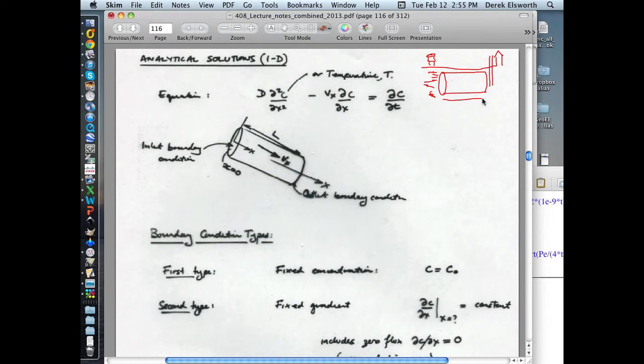then this happens to be the length from the source region to the compliance point, which is the length of this core. There's a velocity, which is an advective velocity along the length of it. And we'll take an x-coordinate that goes through it from upstream to downstream. This point here is x equals 0. This point here is x equals L, uppercase L. And we can try and solve this advection-dispersion equation for that. This is exactly the same expression we just had on the board.